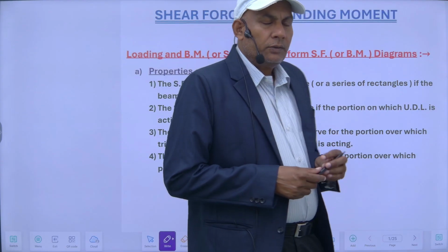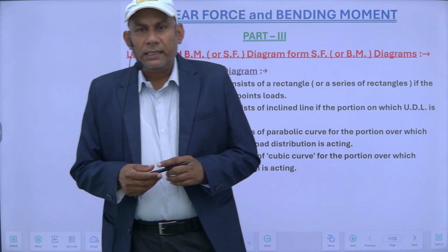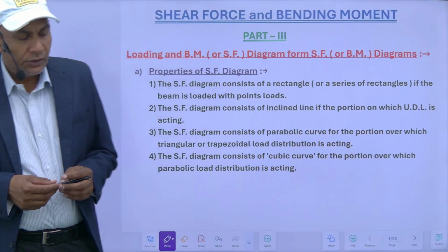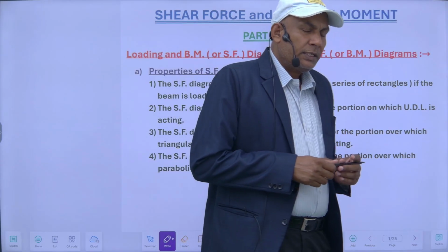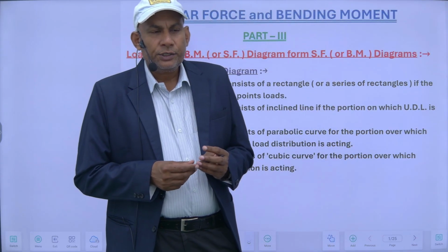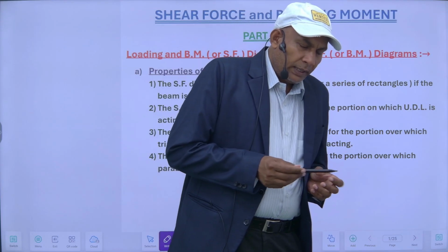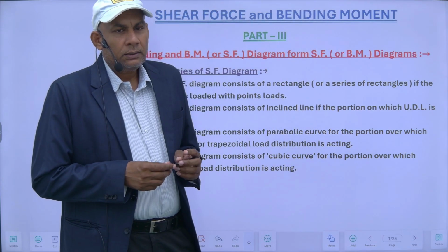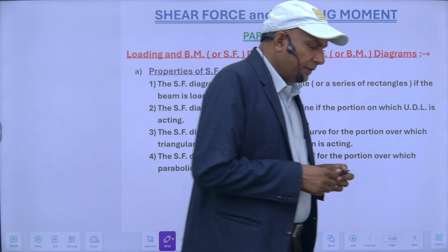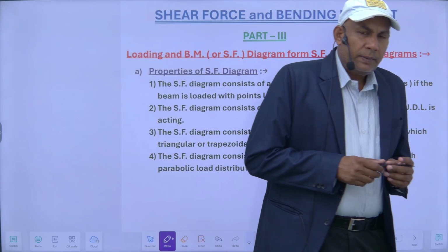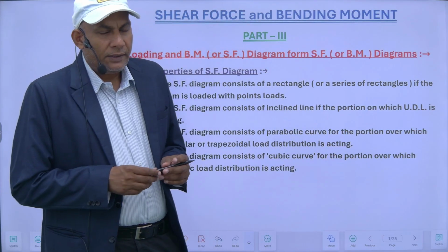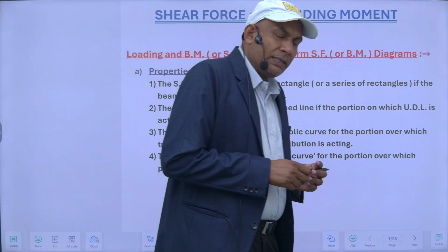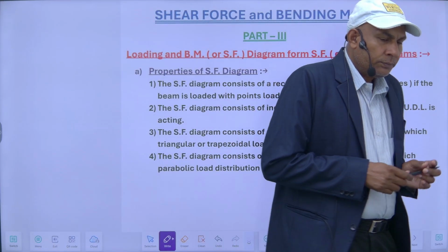So today I am going to give a lecture on the shear force and bending moment diagram, part 3. In two parts I have covered the basics of the SFD and BMD, and the derivation of the bending moment and shear force: the derivative of the bending moment with respect to x will give the shear force, and the derivative of the shear force with respect to x will give the rate of loading.